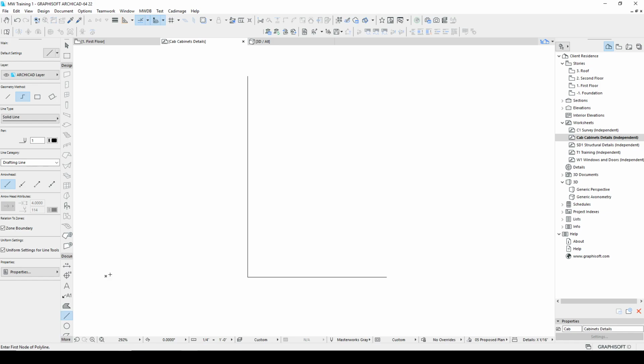So the first thing I do is I begin to lay in some information that I know to be accurate. So I'm going to go ahead and F9 and just copy this to make a ceiling. That gives me the boundaries for my section that I'm drawing here. And then the next thing I'm going to do is just get in some rough geometry for my floor.